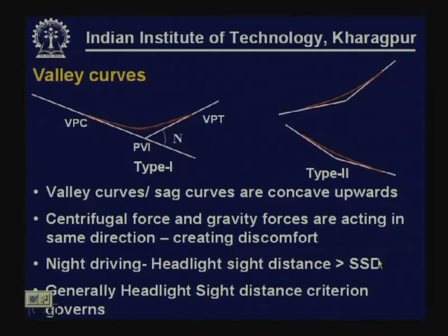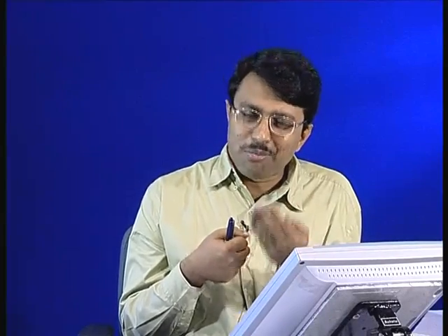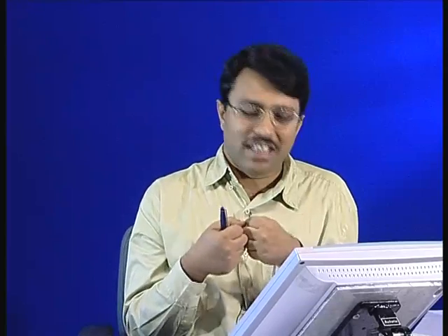Coming to the valley curve, valley curves are concave upward, and centrifugal force and gravitation force are again acting in the same direction. For the same reason that comfort condition is not a major consideration for the summit curve, it is a major consideration for valley curve, because it is acting in the same direction.